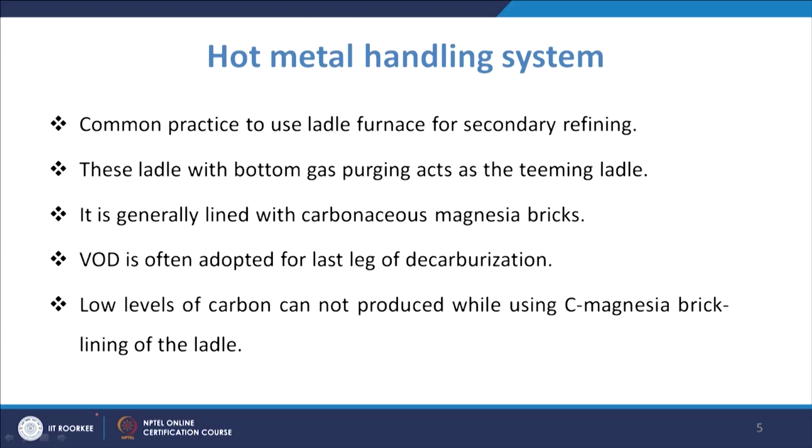Now, the Tundish is the vessel that comes after the ladle. The Tundish receives the liquid metal from the ladle and then distributes it, passing that liquid metal to the mold. So the Tundish is necessary to teem the steel from the ladle to the mold.